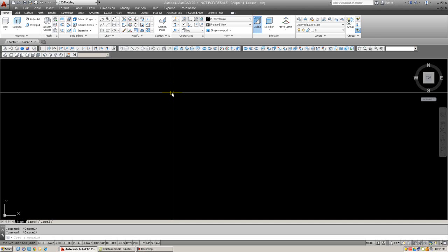Now, in past releases of AutoCAD, the revolve command was a bit picky, and you had to use a closed polyline for the command to work, no exceptions. These restrictions have been lifted, and you can create a profile using a regular line command and even leave gaps in it, although once again, just be aware that this creates surfaces, not solids. And we're going to show that later. Your axis of revolution could be anywhere, on or near the object, and you need not revolve all the way around, but can use any degree value in between if necessary, such as when you want to show a cross-section. So let's put this all together with some examples.